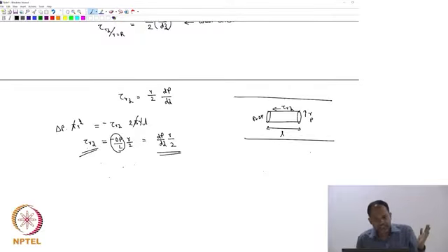So, pressure is trying to push it in one direction, the shear stress is trying to push it in the other direction, and that fluid element is therefore in an equilibrium state, where it is not being acted on by a net force, but it is still continuing to move, because we have already assumed steady state. So, it is moving with a steady state velocity. That is what is actually happening. That's clear?